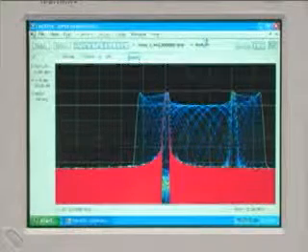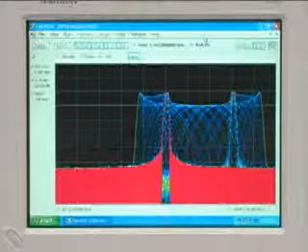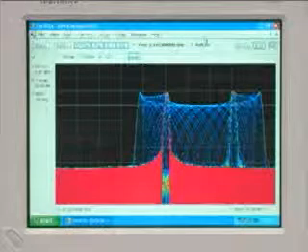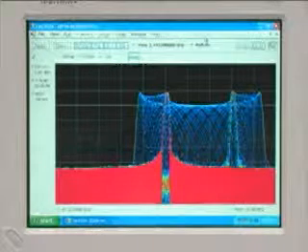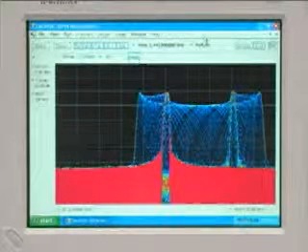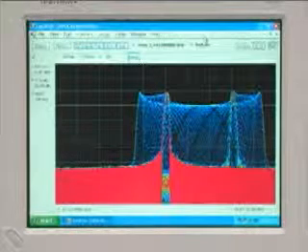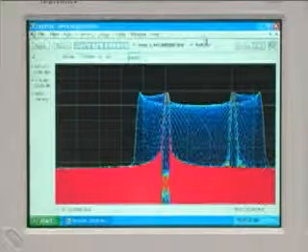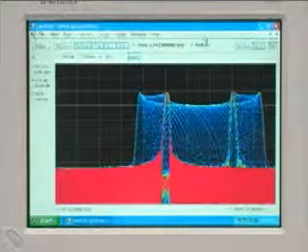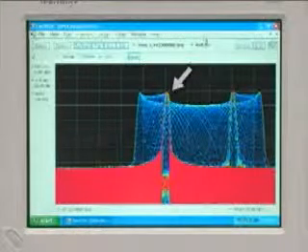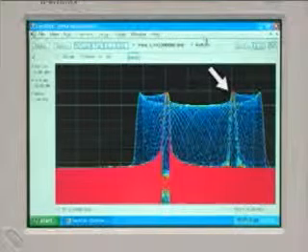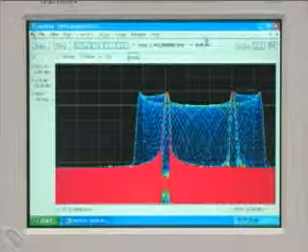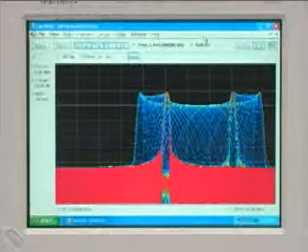DPX allows you to see frequency events occurring in as short a period of time as 24 microseconds. Here we're not only able to see the envelope of this transient signal, but we can also see some specific frequencies at which it appears to be settling, with a transition where it overshoots the frequencies and settles on the new frequency. We can see the main carrier frequency, plus another frequency where the signal jumps, and we also get a waveform buildup showing the actual transition between the two frequencies.